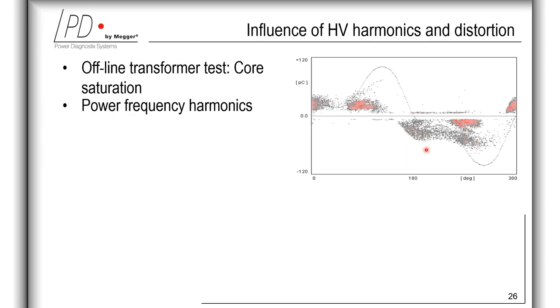And this is related to a distortion of the cavity discharge pattern. The larger scattered pattern in the negative half cycle here is directly showing this distortion. And in the positive half cycle with a higher availability of electrons, it is split into two patterns.